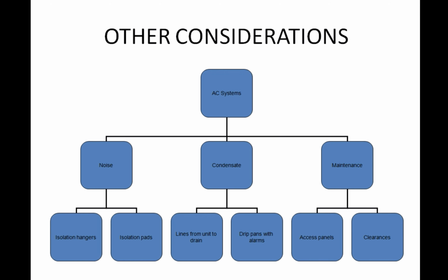and basically you have to accommodate for that. You have drip lines, drain lines in there. Your ductwork will probably have a very minuscule angle to it, so that any condensate or water buildup in it can drain towards one of these. And then there's also pans that fill up with alarm levels if there's an excessive amount of condensate, where either a pump will kick in or you go and drain the bucket or the pan and then make sure it's dry and replace it.